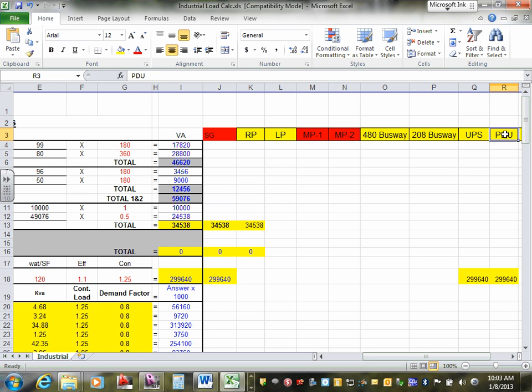Typically, what's a PDU? A PDU is a panel. It's a panel with typically a transformer inside it. A panel and a transformer, they call them power distribution units. The way they design data centers, guys, they take a big fat UPS here and they feed PDU1 from it, and another big fat UPS2, and they feed the PDU2 from it.